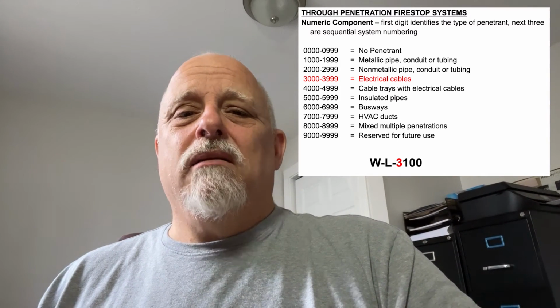Now you're probably wondering, well, why is this really important to me? If you know this system, it's going to help you as an installer because if the estimator gave you a firestop system that began with an F, which is for floors, to use for a wall, then you know that they're giving you the wrong system, right? Or if the second letter was an A, then that meant that the concrete floor was less than 5 inches, where you measured your floor, and it was more than 5 inches. So it can help you identify without even having access to the catalog if you know how to use that system.